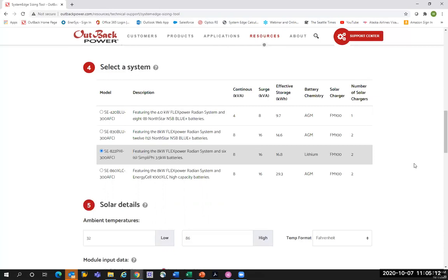And so when I got there on site and I was looking at it, the inverter just wasn't able to handle that surge. So later on, I took a picture of the nameplate, and it was a Baldor motor they had, and I went to the Baldor motor website, and they had a separate spec for inrush. So while the running current was 11 amps and the locked rotor was 17, the inrush current was 87 amps. Okay, so there was no way.